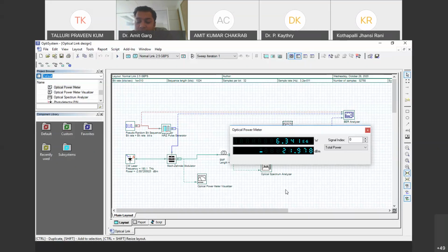Okay, we can say if we are not transmitting some higher power, then the receiver will not be able to get the proper value, a value well above the receiver sensitivity level, so it will give noise. And if we are getting power at the receiver that is above the receiver sensitivity, we get good results. Okay, so 6 dB.